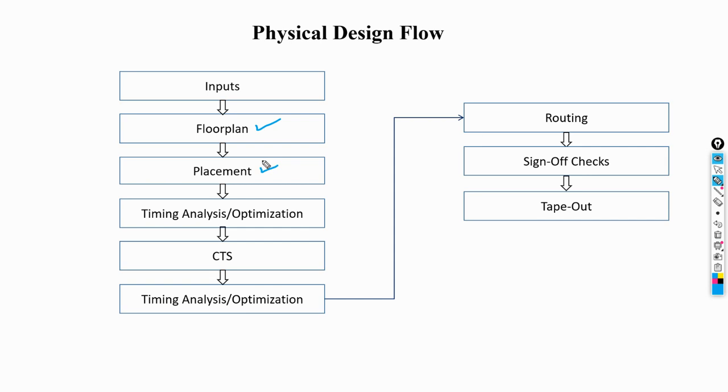There is something called standard cell placement. We let the tool do the whole standard cell placement, and then there are certain things that we look at. When I say things, meaning your timing, your congestion, and utilization, and all of that, you would have to look at it. And then again, you may want to do a timing optimization and all of that.